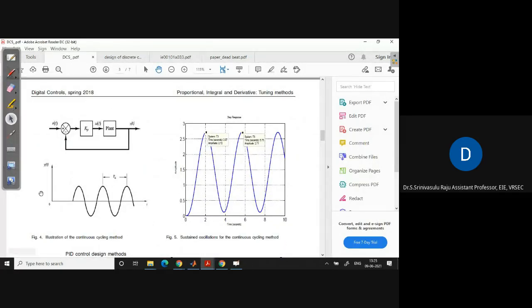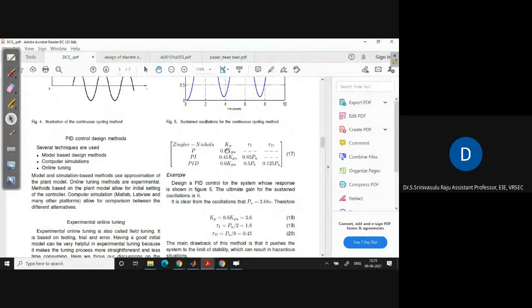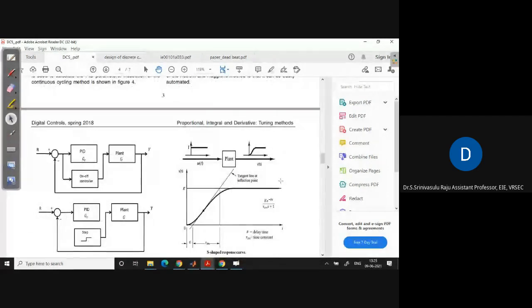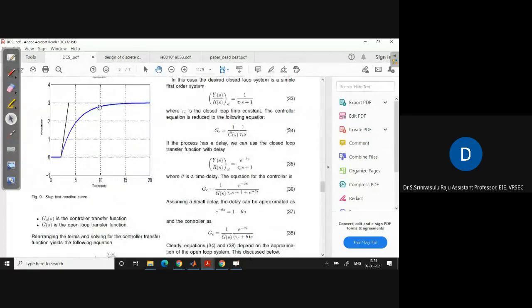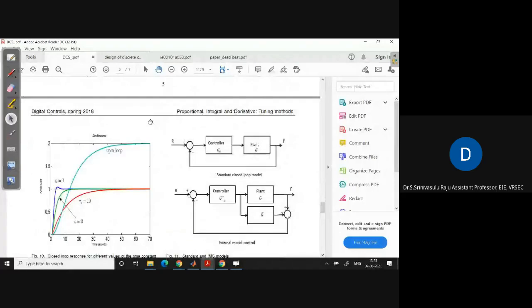So this is the Simulink block, and they have simulated it in MATLAB, and they calculated the PID with the help of the Ziegler-Nichols tuning rule. We have standard tuning rules for PID: Ziegler-Nichols, Cohen-Coon, Lopez method. We have a number of techniques. So they calculated from here. Now they replace D of z with the digital PID, and there is a tracking response like this. Here they implemented both the Deadbeat and Dahlin's algorithms for different set point inputs.